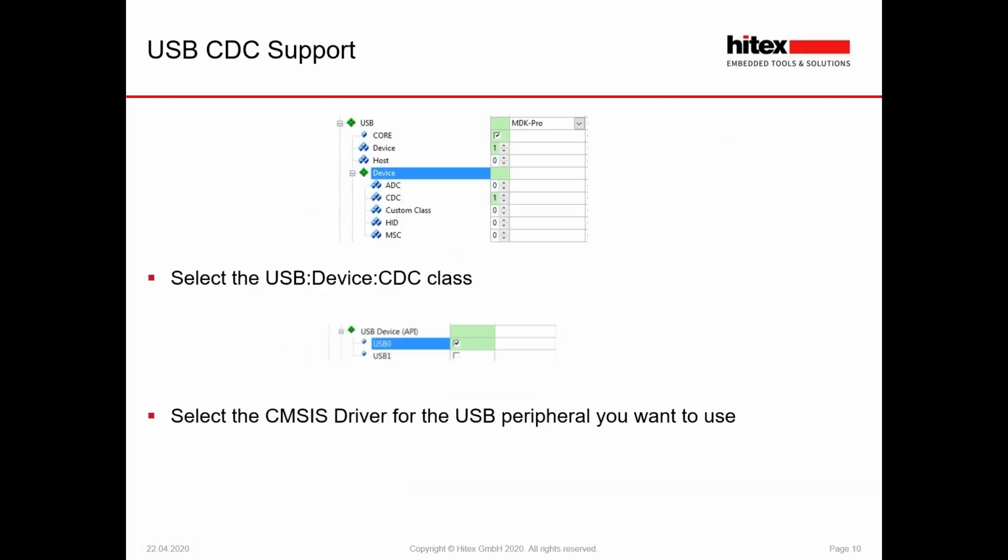Like we did with the networking class, when we are trying to configure, we'll go into the USB section and take the most abstract part of the configuration. In this case, we'd start by saying that we're going to create USB with communications device class support. This will show us any dependencies on that class, and we can start to add them.